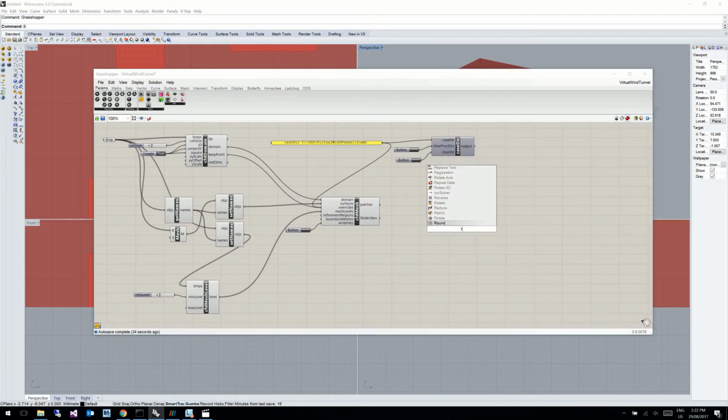So at this point it's actually good to set up a run solver, and you want to run that mesh and inspect what the mesh looks like before you go too much further. So in this case we'll set up a panel and we'll define the solvers that we want it to be blockMesh and snappyHexMesh. I've got a 4-core computer, so I'll define the domain to be divided 2 times in the X, 2 in the Y, and 1 in the Z to give me 4 subdomains that will be divided up for multiprocessing. And in this case, we'll just run it using a button. By default, the cases are reconstructed after the solvers have been run, so we don't need to modify that.